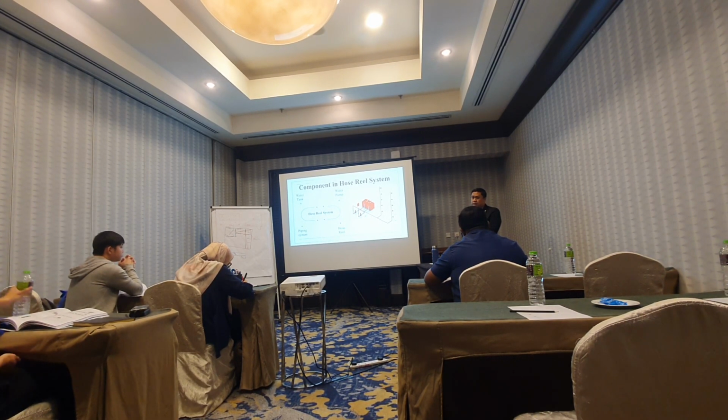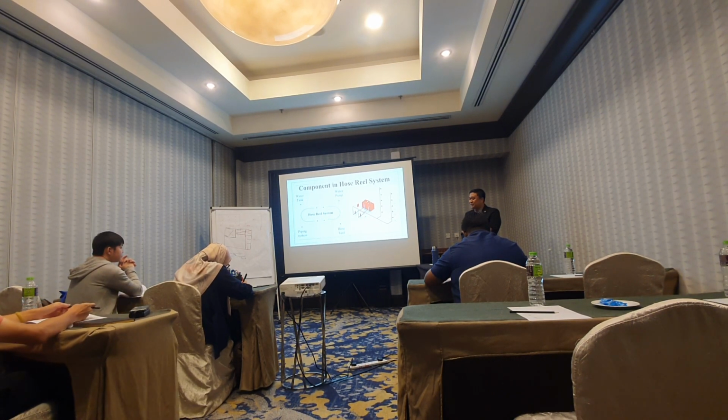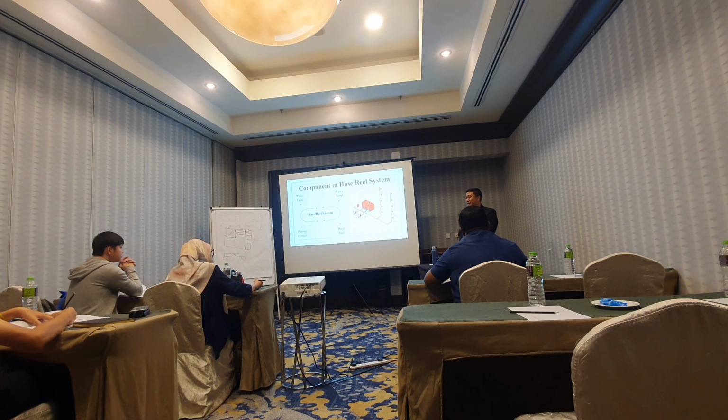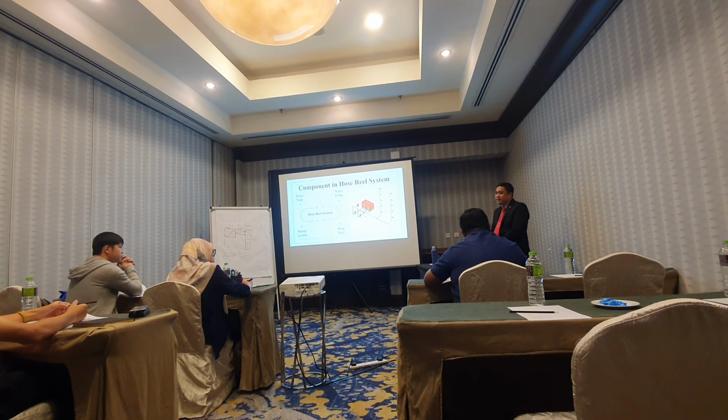So all the pumps need to follow MS 2616 lah. For hose reel system, you also need to follow the MS 2616. But in MS 2616, it's been spelled out that the hose reel pump doesn't require the shock test lah.